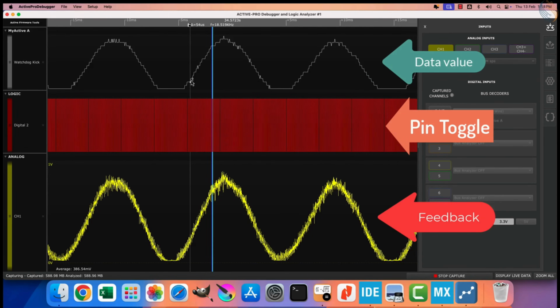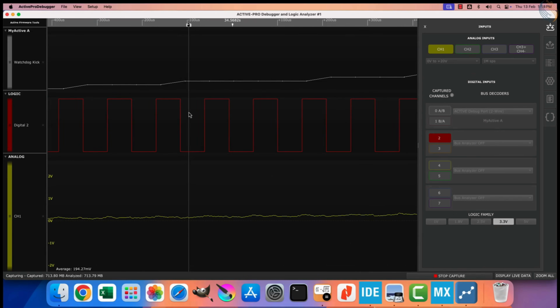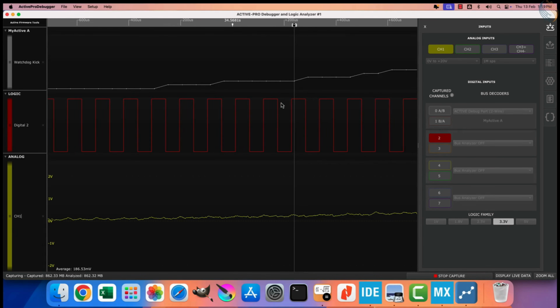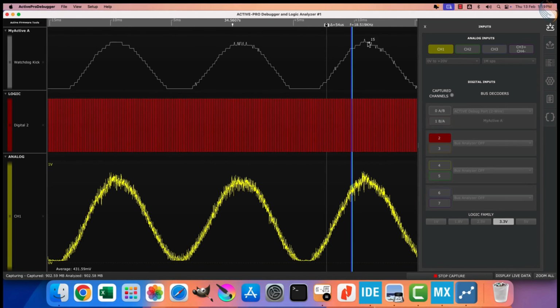Now since we are using 6 bits resolution, there are fewer values available for the voltage variation. Therefore you will see this line remains horizontal for a lot of the time. In fact the voltage at this point is around 168 millivolts, whereas it is around 268 millivolts at the end of the horizontal line. So for almost 100 millivolts, the line remained horizontal at the value 2. Similarly, the line is horizontal for other values as well.